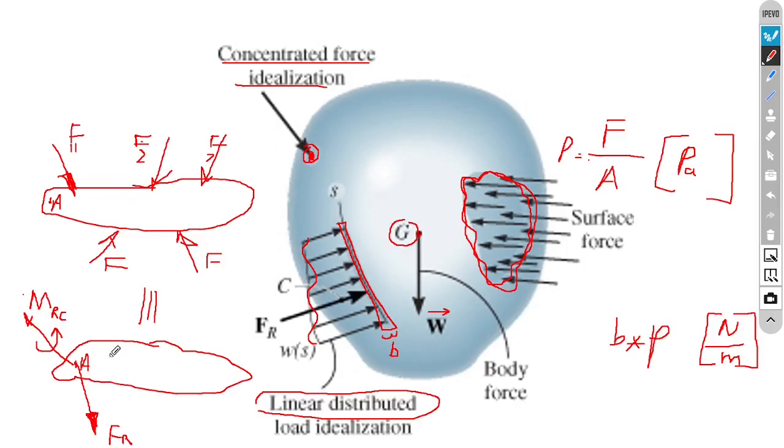If the equivalent system is to be determined with respect to a certain point A, say that instead of applying the forces onto the body, we apply only one force at point A. If we know that the net effect of the given force system is to be determined at point A, then calculate the rotation effects of the forces, the moments of the forces with respect to point A. If we do this, then we obtain a resultant couple over there.